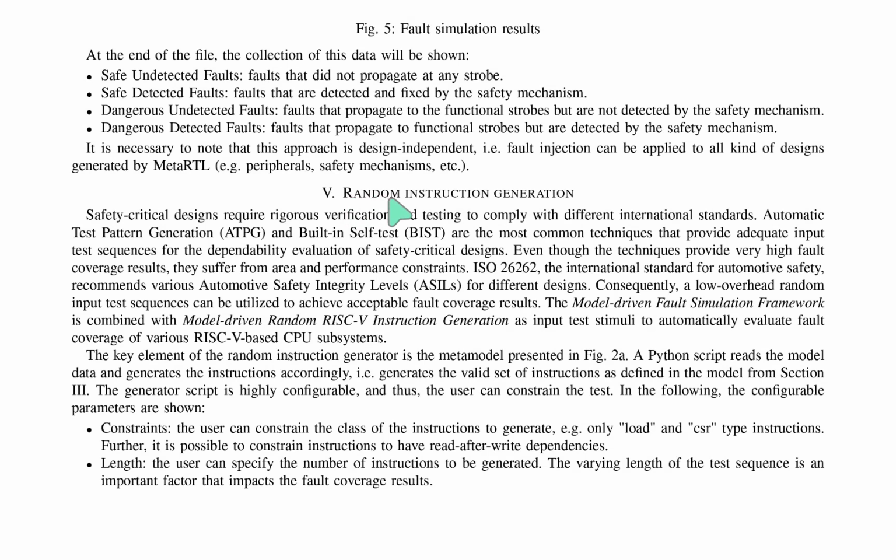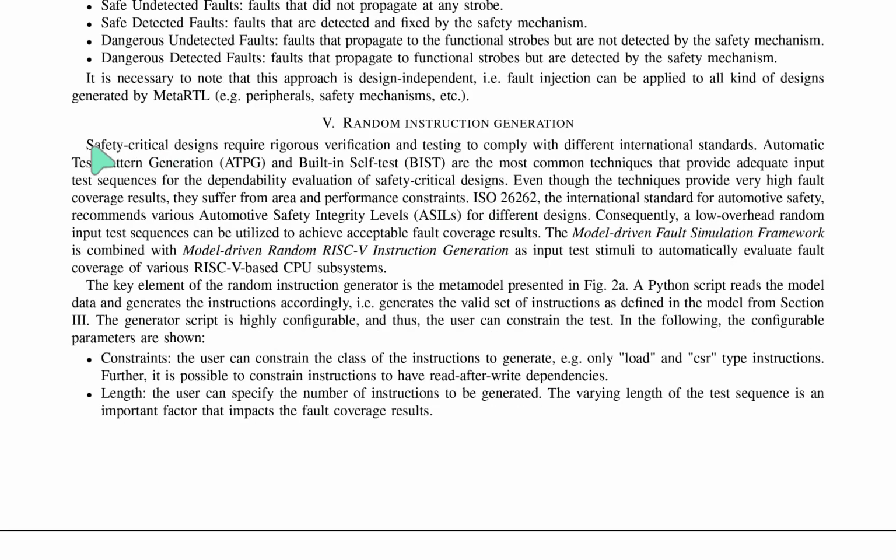Chapter 5: Random Instruction Generation. Safety-critical designs require rigorous verification and testing to comply with different international standards. Automatic test pattern generation (ATPG) and built-in self-test (BIST) are the most common techniques that provide adequate input test sequences for the dependability evaluation of safety-critical designs.